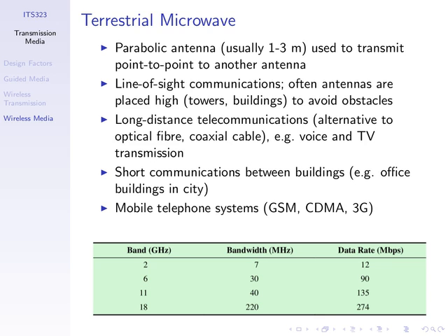When the signal hits a wall, that signal attenuates significantly and it comes out the other side very, very weak and it cannot be received. So if there are any obstacles between the transmitter and receiver, then normally they cannot communicate. Hence we need line of sight communications.